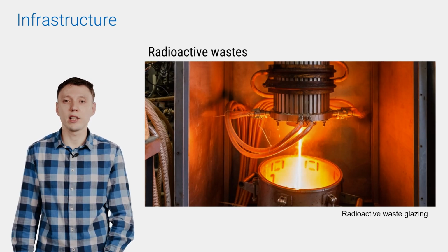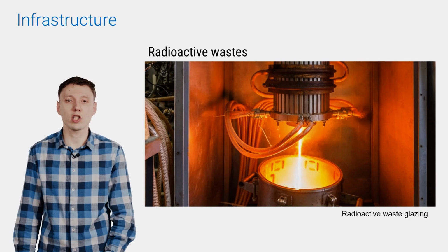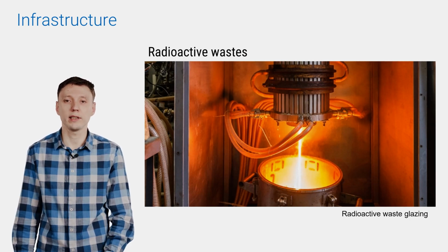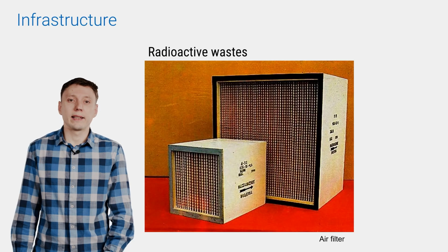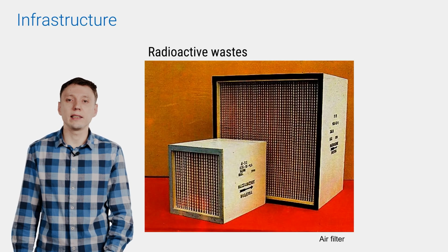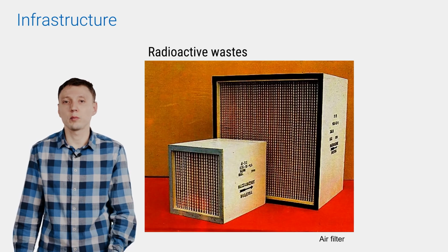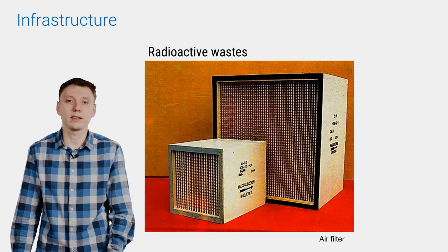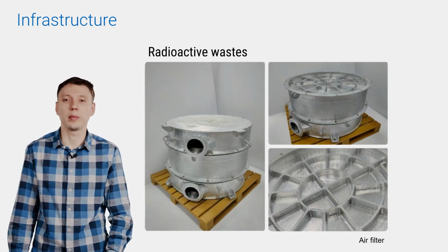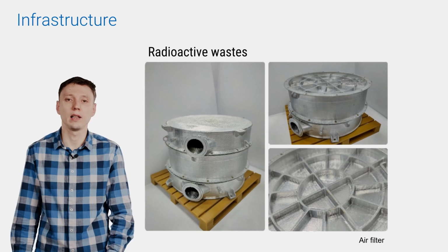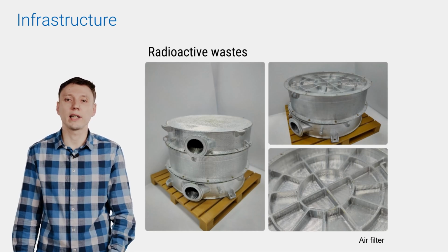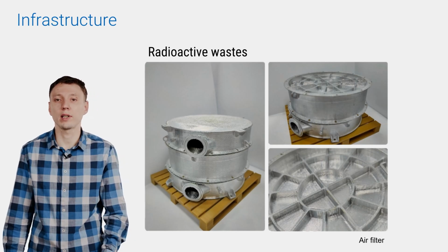A special ventilation system removes gaseous radioactive materials generated during research work. The gas is not immediately released into the atmosphere. First, it may be stored for some time in special tanks and then passed through special filters. After passing through the filters, the cleaner gas is released into the atmosphere, while the filters are disposed of as solid radioactive waste.